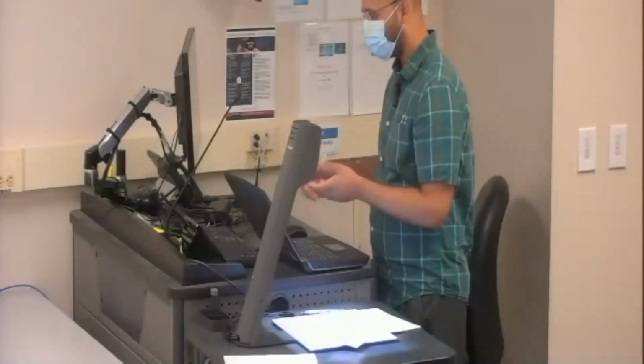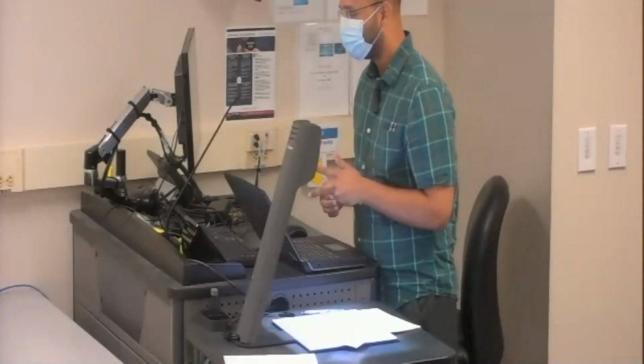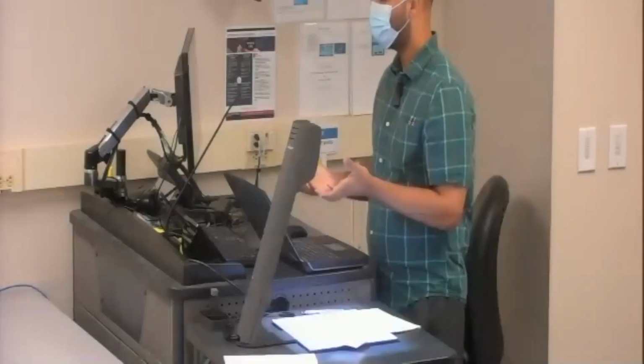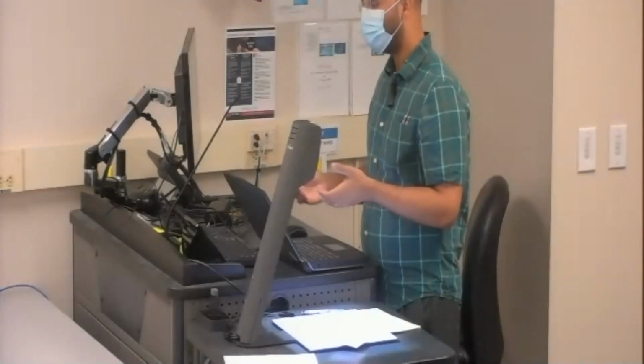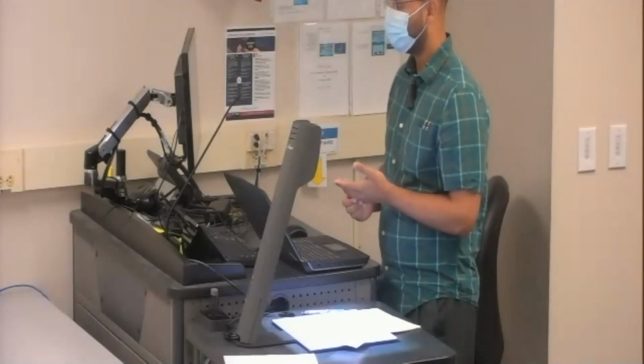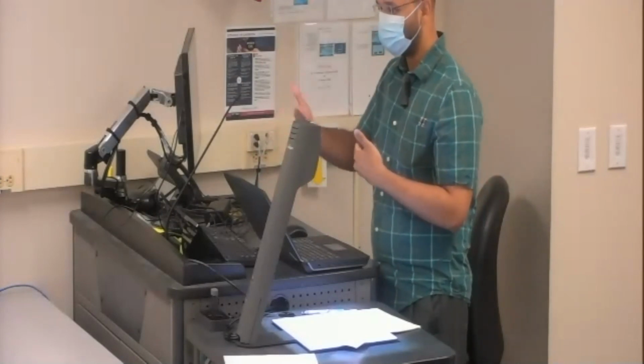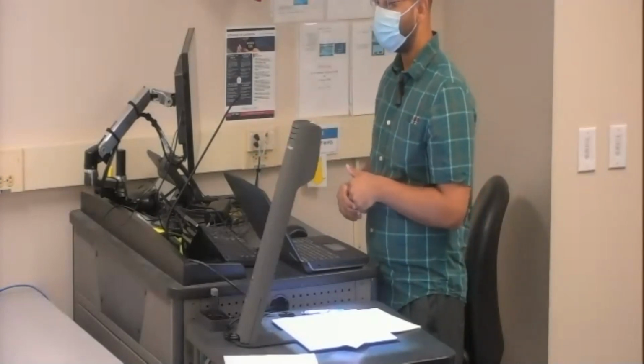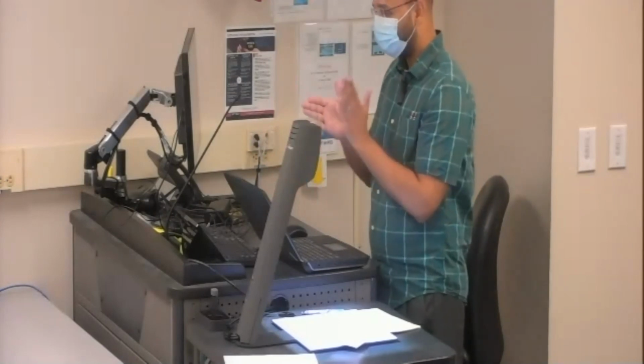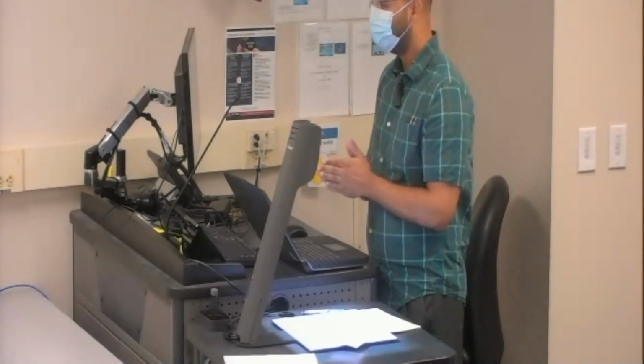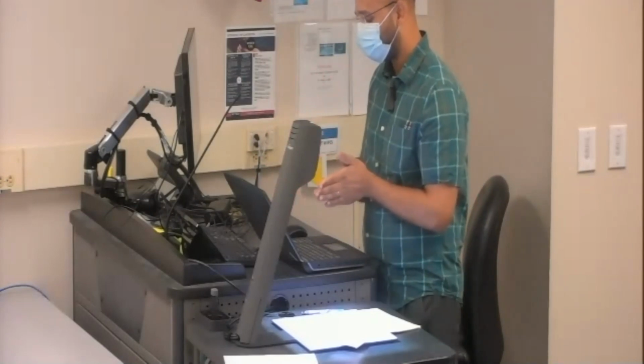So run longer, like 10 seconds or 20 seconds. Saving interval: if you save more files, it'll take more disk space, but you will get a nicer video because you have more frames. Ideally, you want to save like 30 frames every 1 second, but we save 10 frames per second.